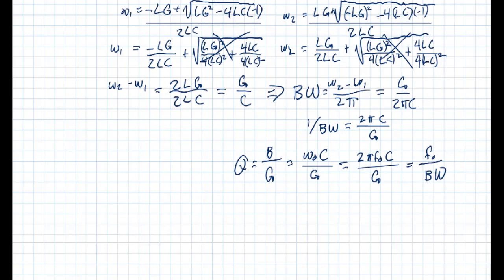So we arrived at an algebraic quasi-derivation of that relationship between the 3 dB bandwidth and Q by setting the magnitudes of the susceptance and conductance to be equal, and then solving for frequencies, the band edge frequencies, using the quadratic equation. And then the bandwidth is the difference between the upper and the lower frequencies.